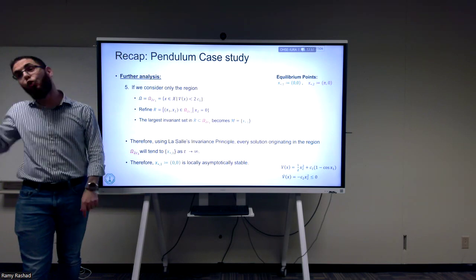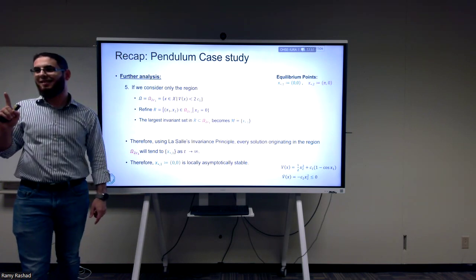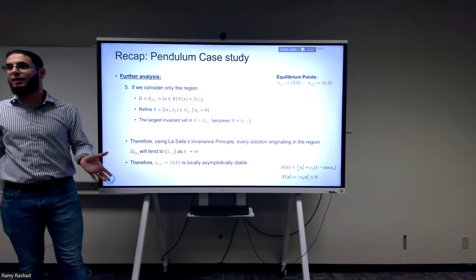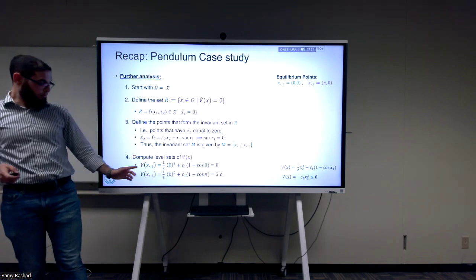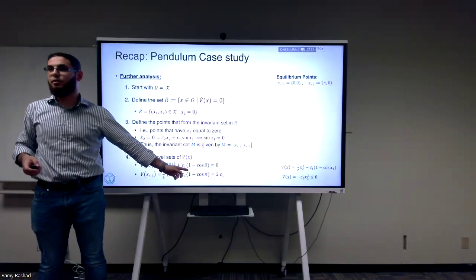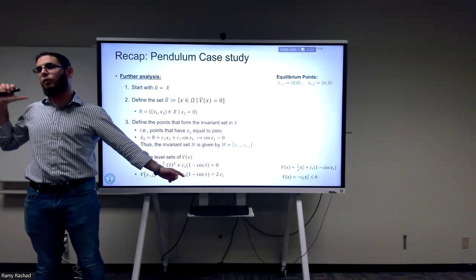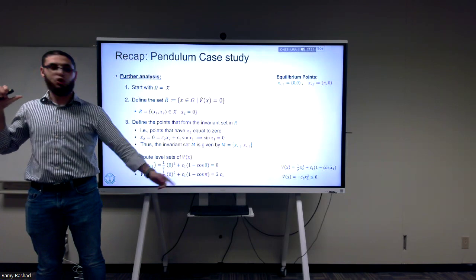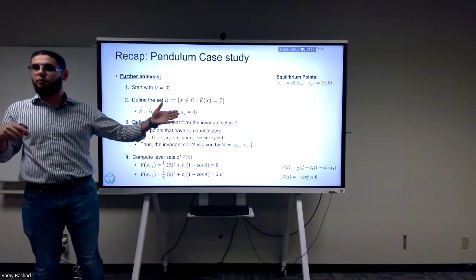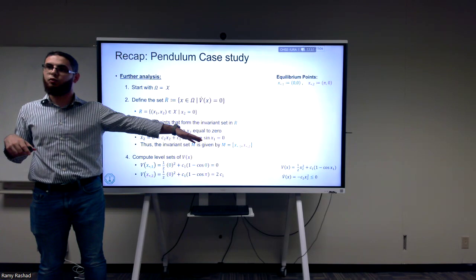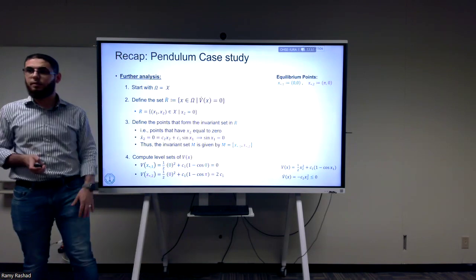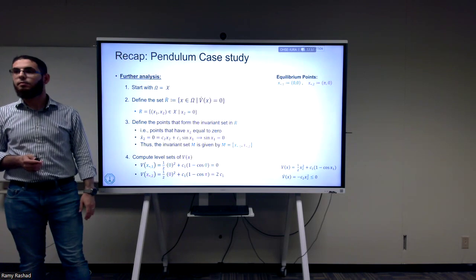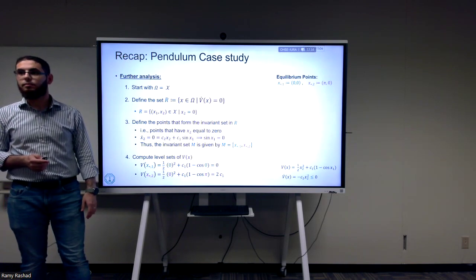If it's truly locally asymptotically stable. If it's not locally asymptotically stable in the first place, can you try to do the same for the other equilibrium point and reach the same conclusion? It's impossible. We already know from Lyapunov's indirect method it's unstable. So no matter how hard I try with other Lyapunov functions, I'll never be able to do that. That's the idea. The alternate question now is for global asymptotic stability: can we still reach the same conclusion?